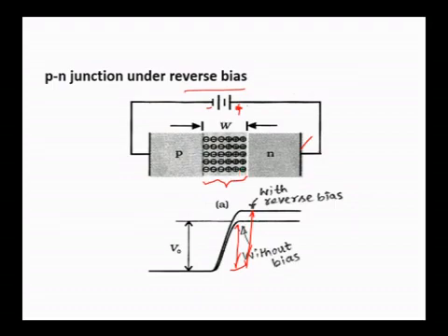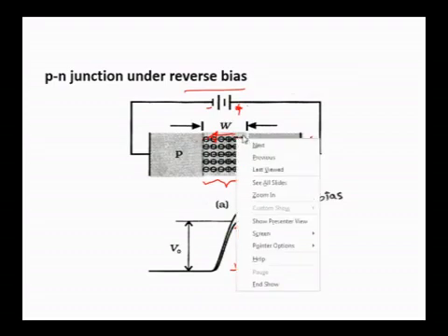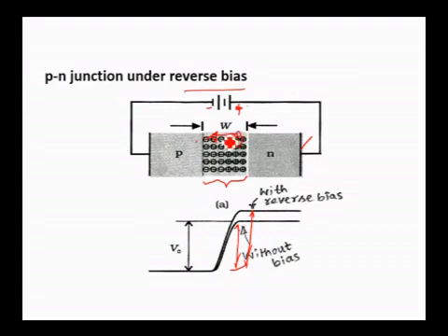Like a drift is going to happen in reverse bias because this particular plus and minus ions will develop a field in this direction. So plus ions piled up here, minus ions piled up here, plus to minus, the direction of the electric field will be there. So in that sense, N-type side will be at a higher potential, P-type side will be at a lower potential. This field can cause the drift of charge carriers, minority charge carriers, and drift is the major process that happens in reverse bias. Diffusion is the process that can be the mechanism for conduction in the forward bias.